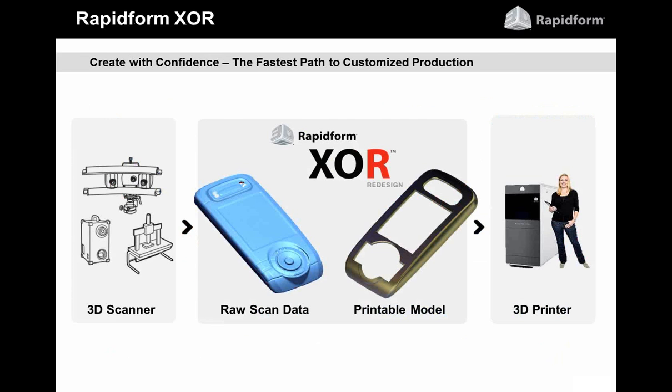One thing about Rapidform is that it is software to create manufacturable CAD models, which are actually parametric, from native scan data. So we can use any point or mesh creation device, whether it's a CMM or an optical scanner or laser scanner or any other device which can generate point clouds or meshes.